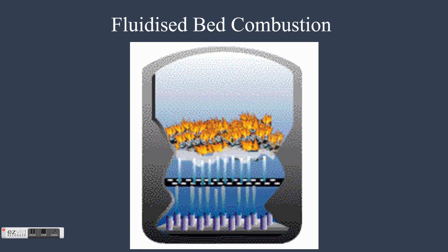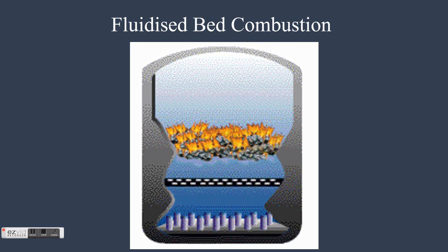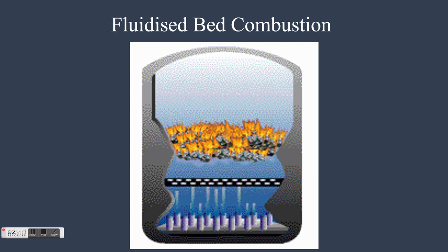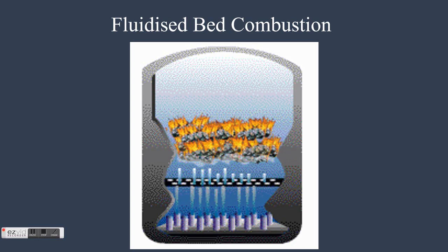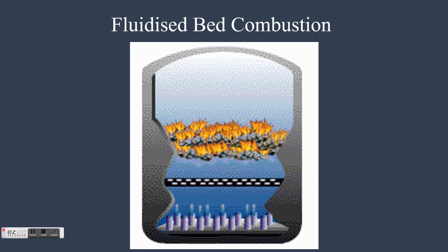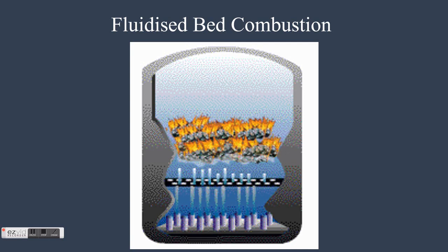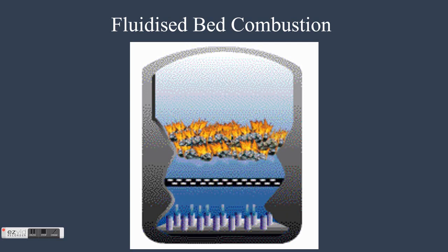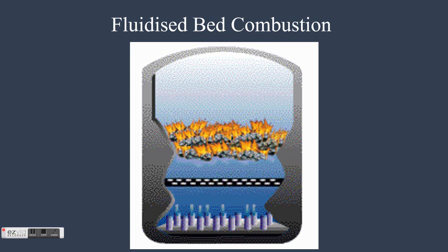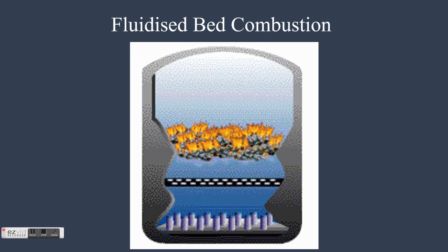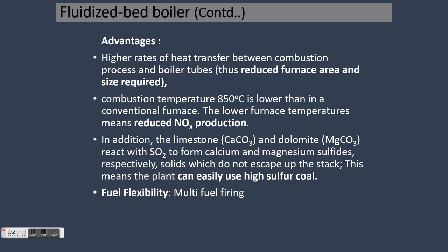Ash is disposed of by dry and wet ash disposal systems. Fluidized bed combustion has significant advantages over conventional firing systems and offers multiple benefits, namely fuel flexibility, reduced emission of noxious pollutants such as SOx and NOx, compact boiler design and higher combustion efficiency. Advantages and disadvantages of the fluid bed boiler are discussed. Please go through it by yourself.